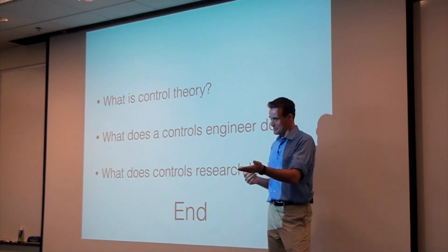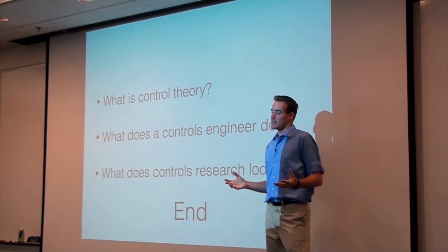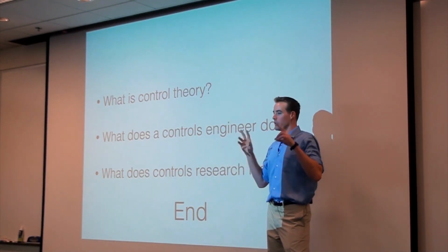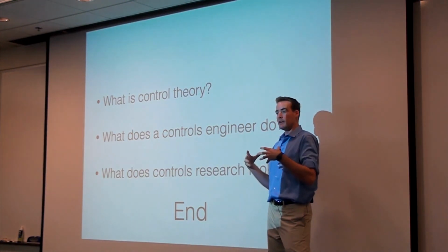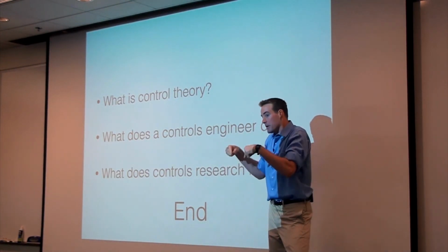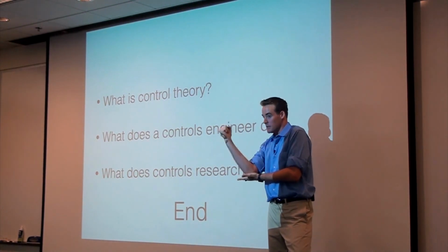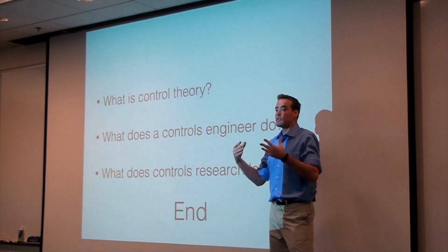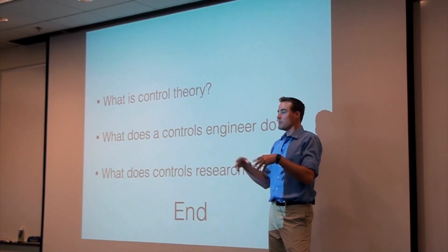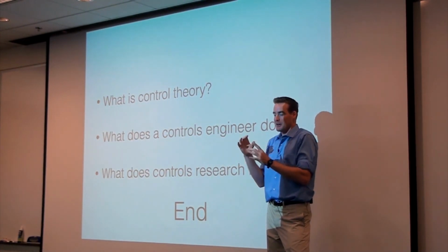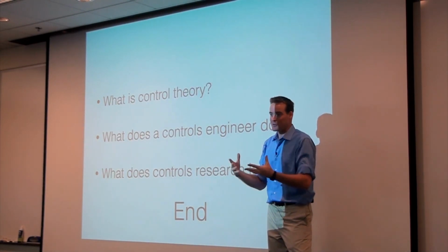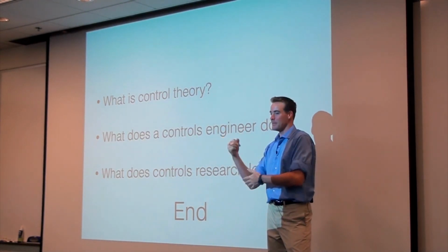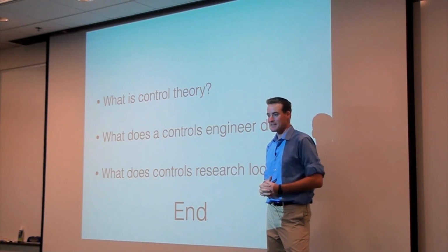But instead, we teach the students in EC 147C another technique: they build what's called an observer. This is a mathematical object that uses the knowledge of the things that you are measuring, the position of the cart and the angle of the pendulum, and the knowledge of the dynamics. There's an internal simulation of the pendulum inside the controller that, based on that internal simulation, can determine the derivatives of those things.